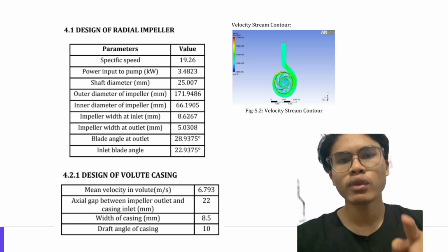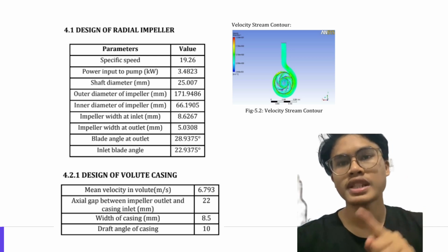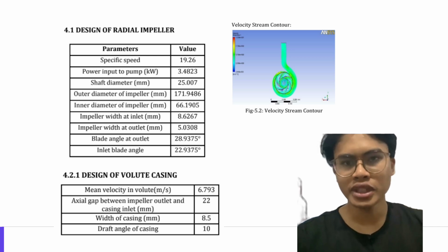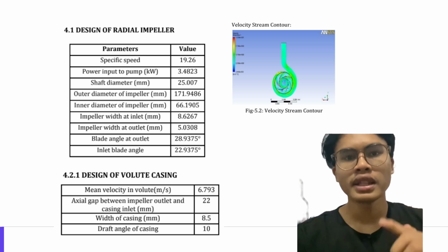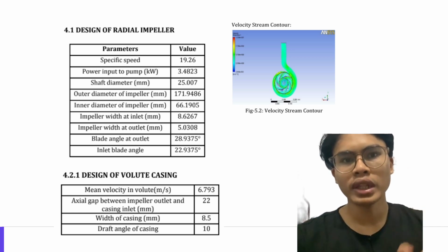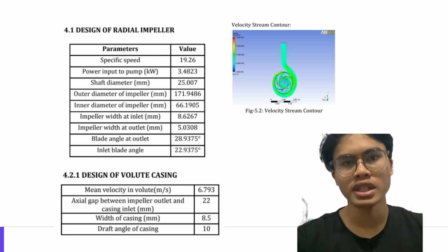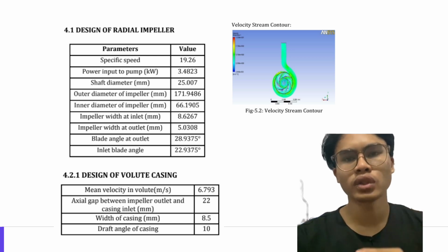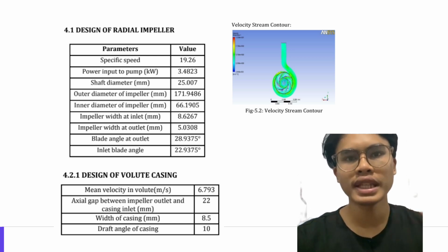The working fluid was water at 25 degrees Celsius, and for turbulence modeling, they utilized the k-epsilon model with a 5% turbulent intensity. And finally, the meshing process was extensive. The pump assembly was broken down into a staggering number of elements and nodes for the CFD simulation. Specifically, the mesh comprised over 5.8 million total elements and 1.1 million total nodes, ensuring high fidelity in the simulation.